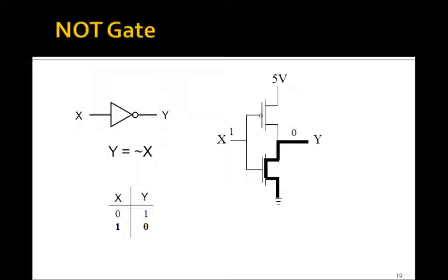So that works. Now, the reason it works is because the PMOS transistor likes to be connected to 5 volts, and this NMOS one likes to be connected to ground. That is, if you tried to put the NMOS one up here, then you wouldn't get a very good short circuit, and the same if you put the PMOS one down here. So in this case it worked.